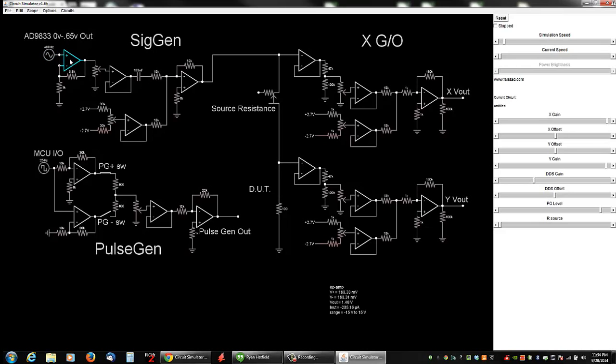Goes through this op amp here. About a 7.8x gain. Going to have a digital pot right here, which is basically attenuating the signal to this buffer. AC coupled, this 10K resistor forms part of the gain loop for this.